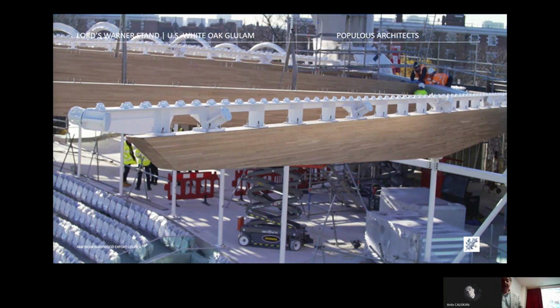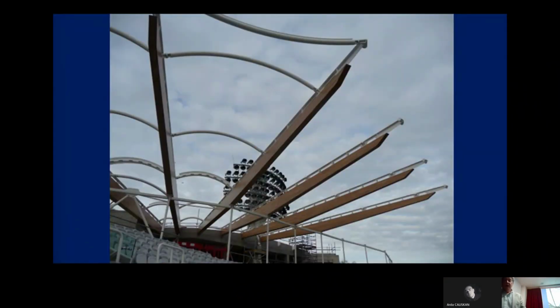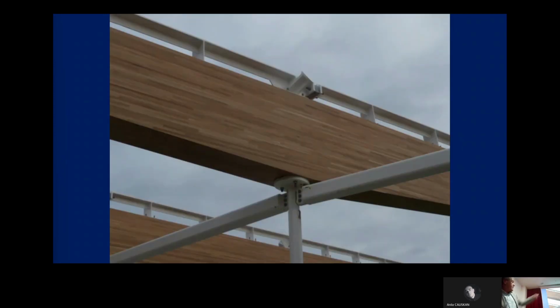So we have 11 of the biggest cantilever beams in Europe. The cantilever sits on the stanchion and is 12 metres back, connected to the wall, and then the 12-metre cantilever sits out under the canopy supporting the roof. They are a metre deep at the deepest point where it sits on the stanchion on the support, 300 millimetres wide, and each weighs about 4 tonnes.